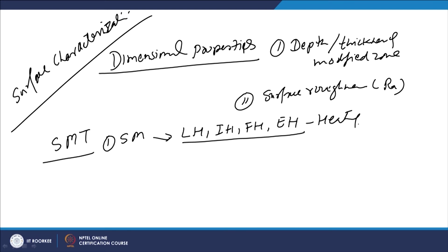for improving the properties. So, there is no reason for variation in the surface roughness in this approach after the hardening, except that due to the heating, if some oxidation is taking place, that will increase the Ra value.